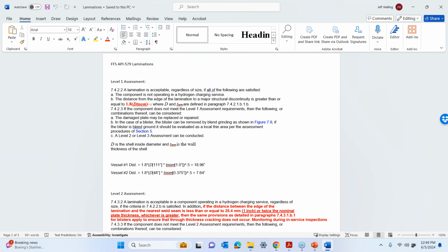Great. Here's another one for you, Jeff. Does it have the ability to perform external pressure vacuum calcs? Yes, absolutely. Just exactly in accordance with ASME Section 8, Division 1. That's pretty straightforward. Awesome.